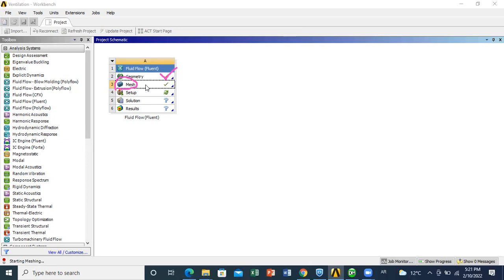Mainly, we have face sizing, which means we can decrease the size of elements. In this way, we go to finer elements, and we avoid, if you want, problem regions. In general, if you have a lot of curves and you use big elements, you might not be able to capture the curvature in your space, and this will give you a bad quality mesh.